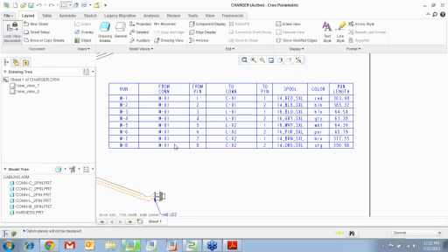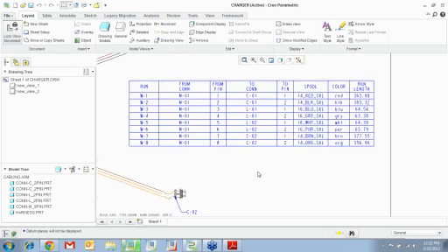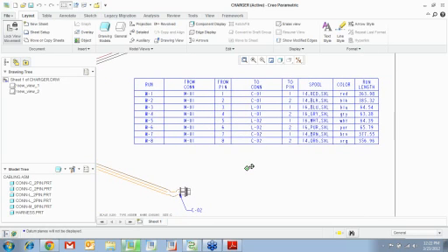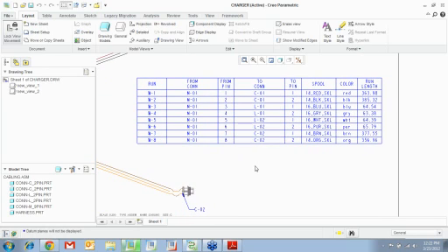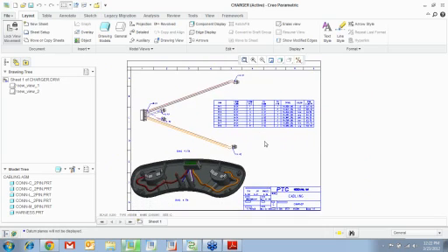All this information about each and every wire can be shown. This is read from the routed system designer into ProEngineer and from ProEngineer into drawing using the repeat region parameters. All right, so this would be your cabling drawing that you might want to have.